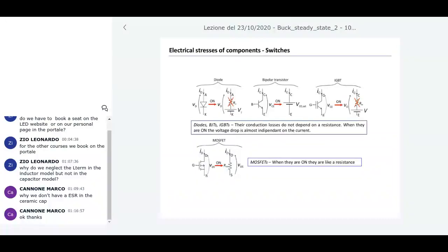If you are able to avoid overheating the electrolytic capacitor, maybe its life can last longer. So anytime you have electrolytic capacitors, we have to choose the value, of course, but what's more important is to understand the equivalent series resistance.